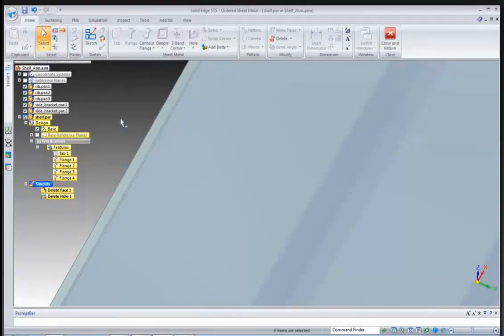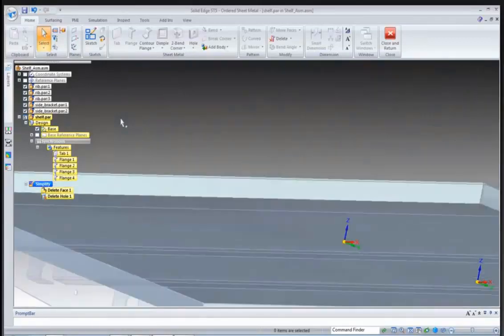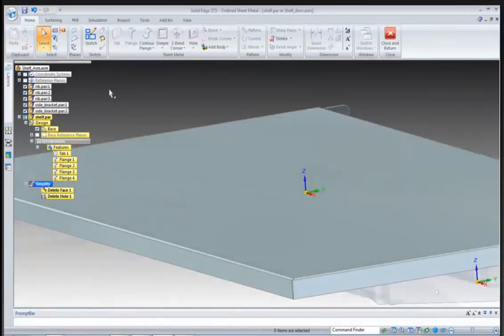I'm going to have a whole lot of elements driving up my solve time, which is exactly why we have the surface element. Surface element is not a 2D element. People always say that because it's represented by a surface, but the reason for that is because you only use 1 through the thickness because it does have the rotational degrees of freedom.